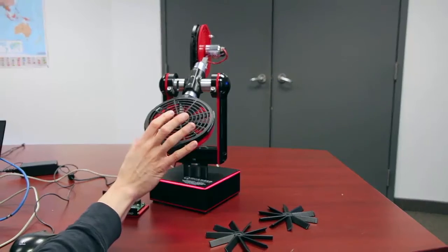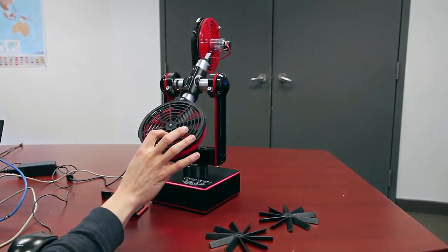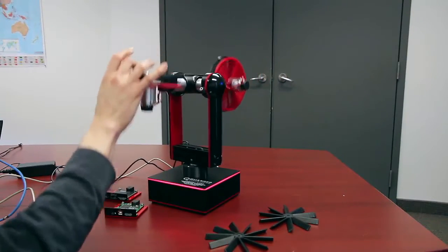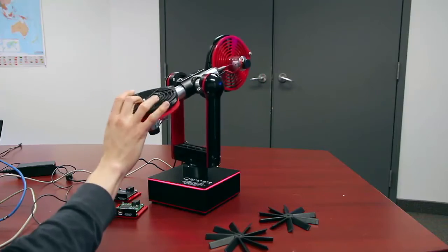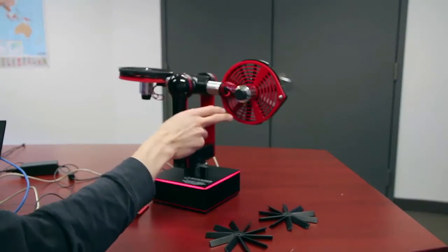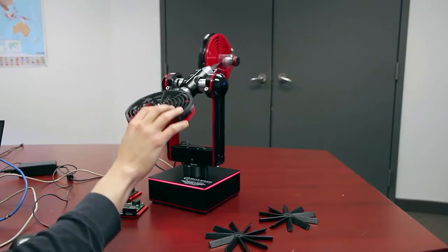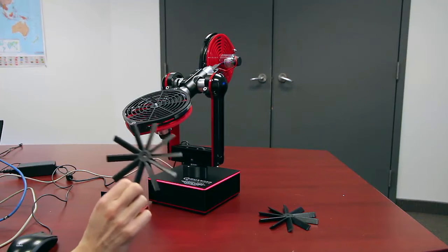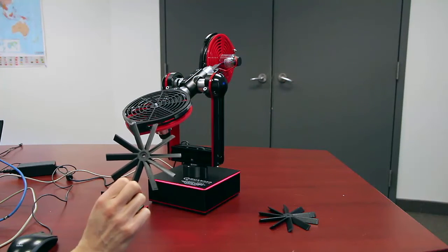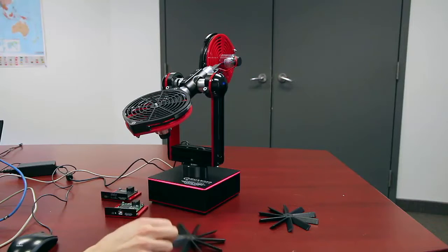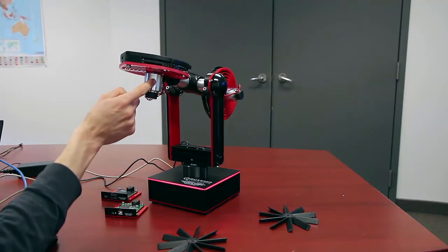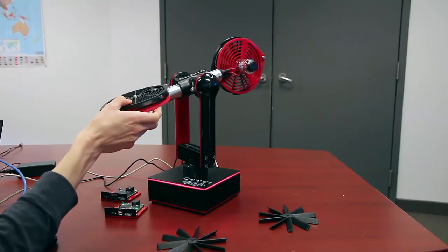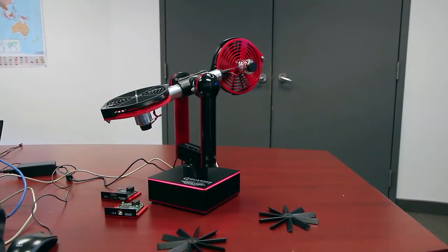This is the main or front rotor. Right now I have it in the 2-DOF helicopter setup. This will control the pitch predominantly, and then we have the tail rotor, which is the yaw. The propellers I have here are the ones shipped with the system, the default propellers that come with the AERO. Each rotor is driven by a DC motor, so you have full access to the voltage of each of those motors.